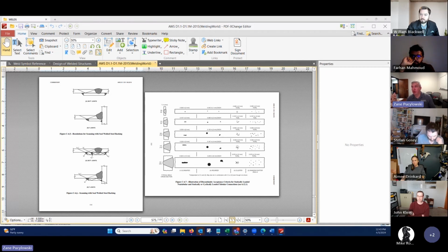And it's more time, more money, more expense, and more chance of warping and things not fitting up well, right? So like that weld a minute ago with 18 passes, if I needed that perfectly flat, I'm probably going to have to put in some stiff backs and things while they're welding it together.